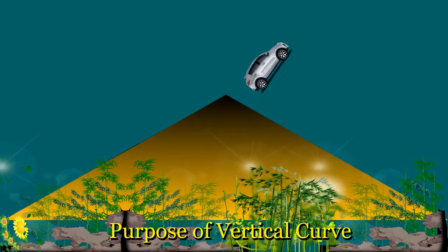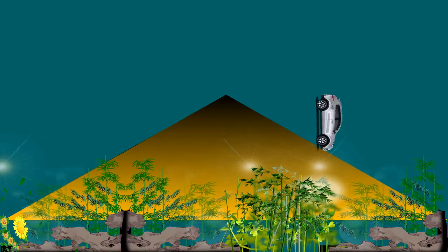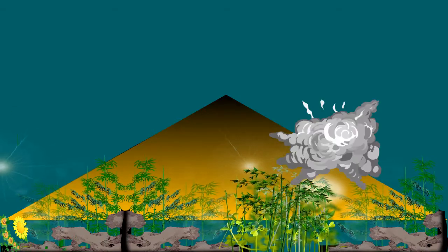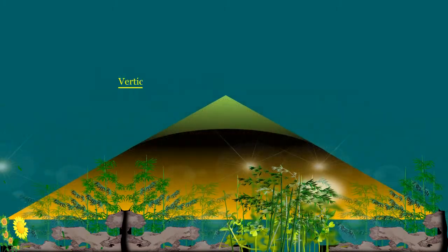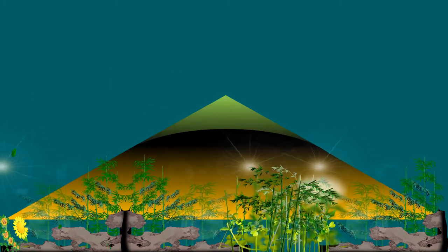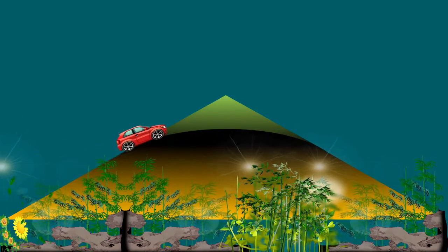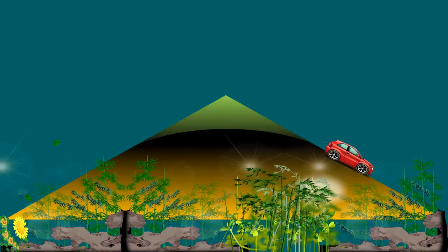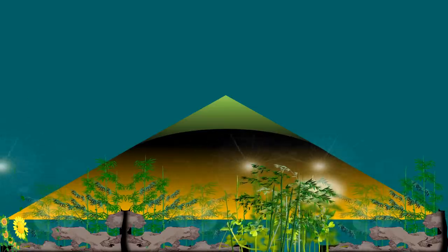On highways, an abrupt change in the grades of vertical alignment will make a big impact on the vehicle passing over. That will lead to either injuries or danger to the vehicles. To avoid this danger, and to smooth out the change in vertical motion, vertical curves are introduced to join two intersecting grades. These vertical curves provide a smooth transition between two sloped roadways, and allow vehicles to negotiate the change in the grades gradually, rather than a sharp cut. Thus, they contribute to safety, comfort, and appearance.